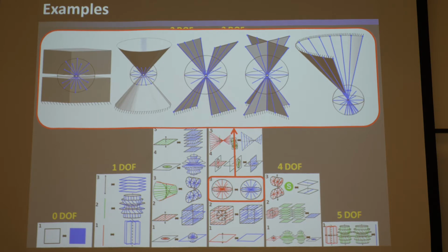Imagine geometries of elements that contain blue lines within the constraint space of the sphere that directly connect its two rigid bodies together, pass entirely through its geometry, and never exit at any point, right? And can be totally filled with blue lines. So it's a parallel element, and make sure you just pick enough blue lines in there that there's three independent ones. So the things that satisfy those conditions is this nub flexure, which is essentially like a wire flexure that's super short.